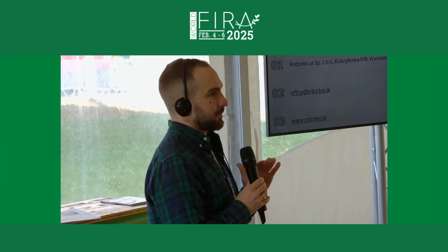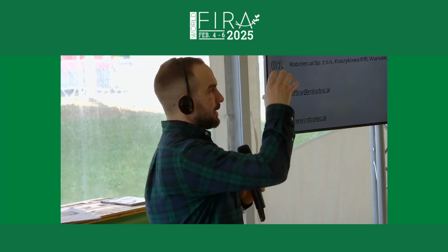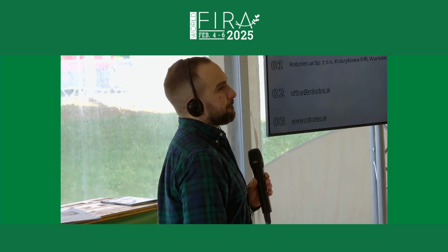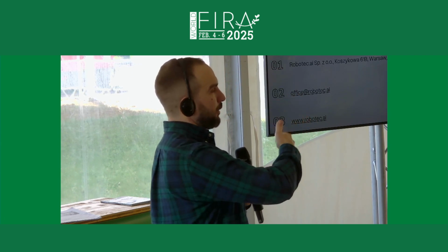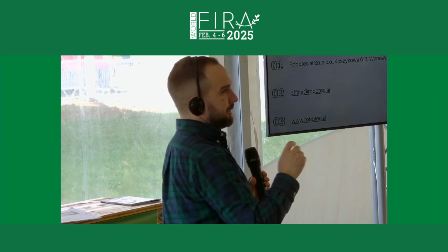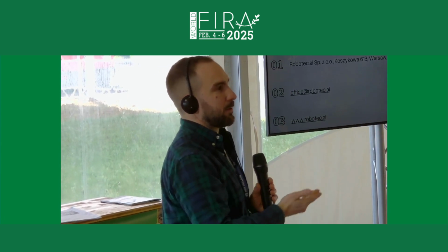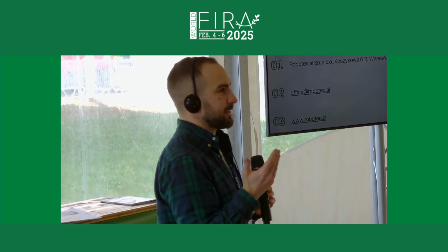That's our default communication. So all data types in ROS2 are supported in the simulator? Yeah, usually, for example for LiDAR, we just send a PointCloud2 message from the simulator. You can subscribe to it and send back control messages, or Ackermann steering or something like that.